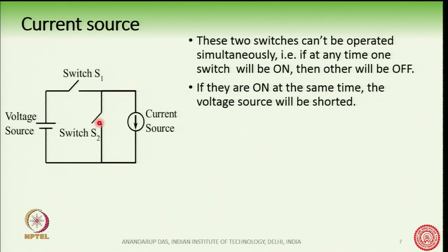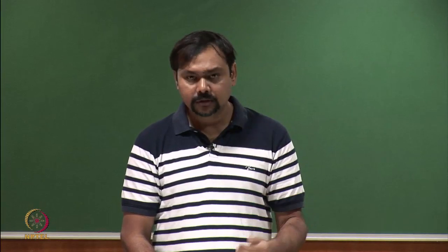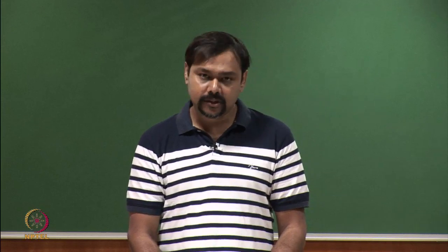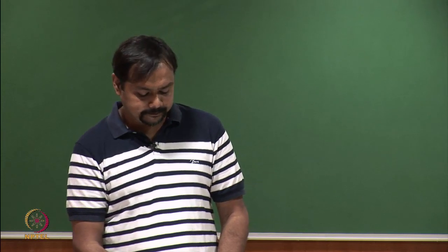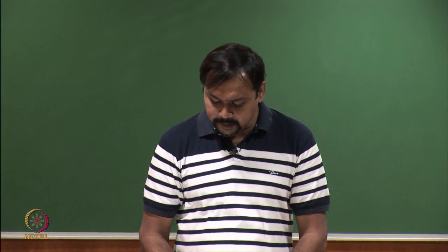So, therefore, these two switches S1 and S2 must be operated in a complementary fashion, like when S1 is on, S2 is off, when S2 is on, S1 is off. They must be operated in the complementary fashion.